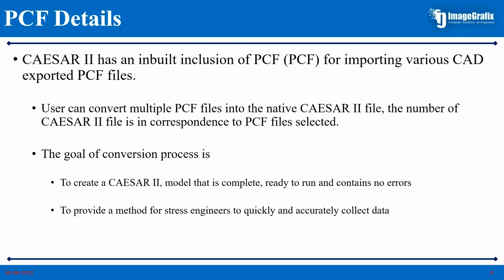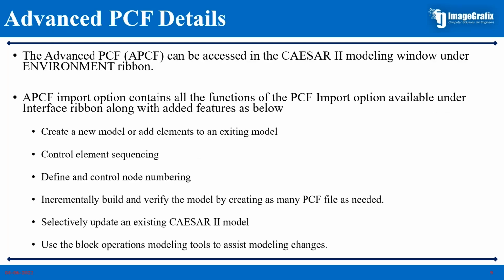So there's one more import called the advanced PCF import, which is located inside the CAESAR window in the main modeling window of CAESAR under the environment ribbon. With this advanced PCF import, along with the options which are available under PCF import, we have additional options like create a new model or add elements to an existing model.